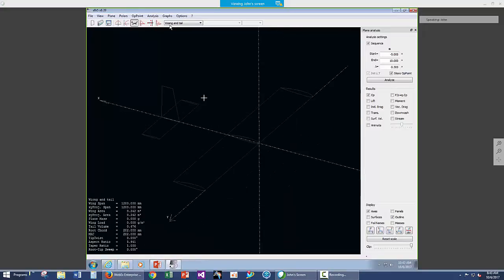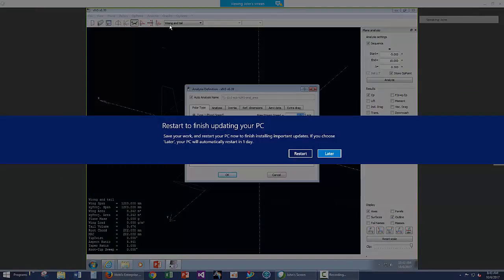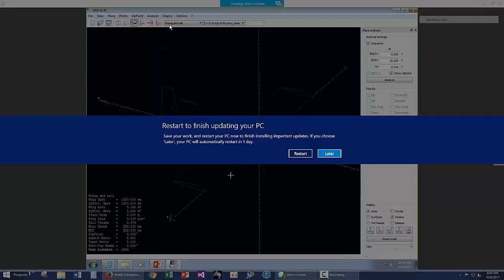We need to do exactly what we did before. We need to do analysis. We've got to define an analysis. We've been running at 10 meters per second, fixed speed, horseshoe vortices, inertia, use the airplane's inertia that's in there, same reference dimension, same aero table. Okay, so that is then the wing, and we're going to run the same case, -5 to 10 degrees.